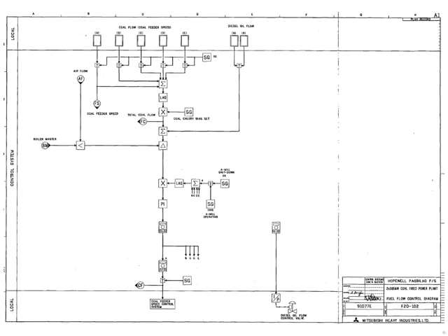A bias logic signal is automatically set up between the two that looks at the fuel demand and the number of coal feeders and warm-up oil burners in service. This establishes the amount of change each flow, both coal and fuel oil, is controlled to. Do not be confused if you cannot see those things I've said in this diagram. We will discuss it on the next slide.